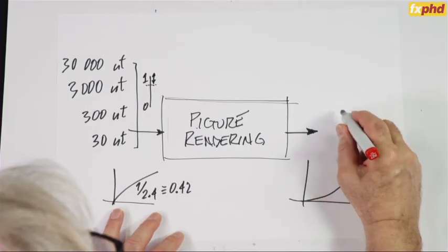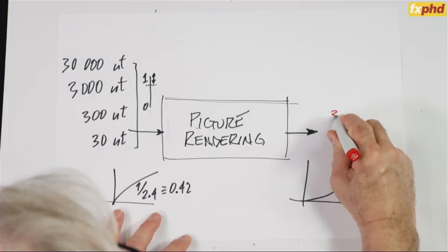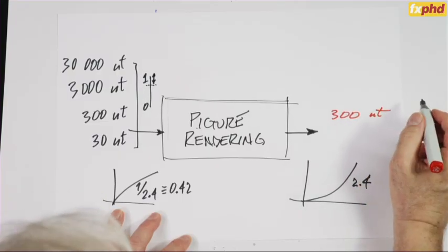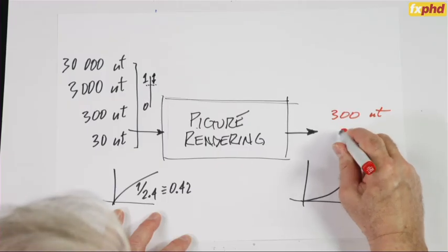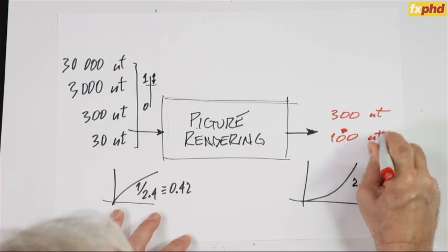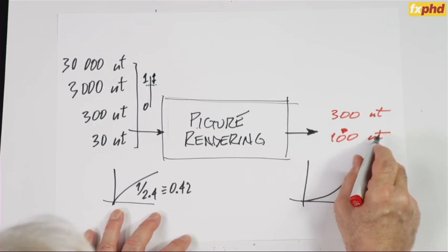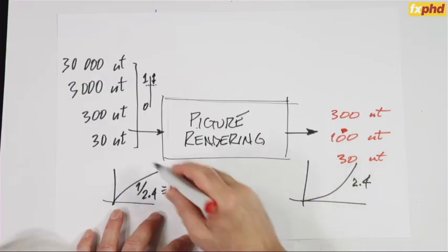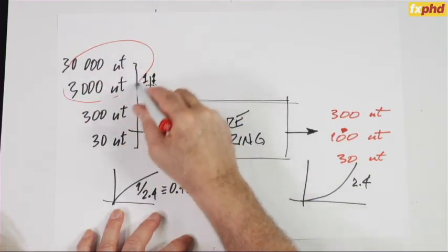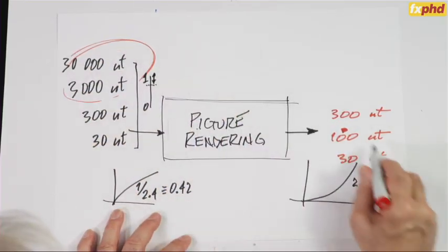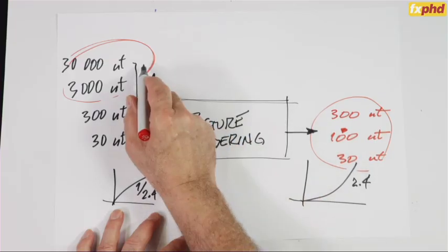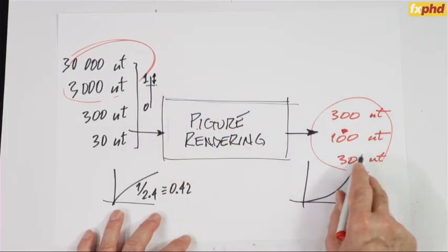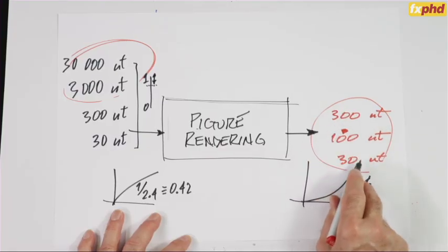Because when you go out, you might be displaying consumer electronics with a white at maybe 300 nits. This would be a typical television set. HD studio display has got a white luminance of about 100 nits, and cinema has got a white luminance of maybe 30 nits. And there's a huge viewing shift from luminances like this to luminances like this. And basically what happens is colorfulness is lost at these lower luminances, and contrast is lost.